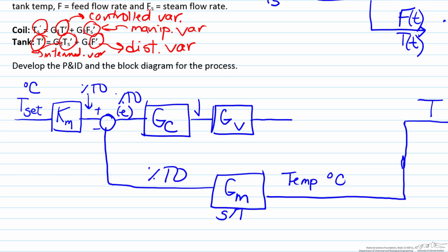What will then be reported to the controller, what will come out of the controller, is some percent controller output. That percent controller output corresponds to how open the valve should be, 25% open, 60% open, etc. And that openness of the valve corresponds to the flow rate of steam. So therefore, we have the first of our variables present, which is the flow rate of steam.